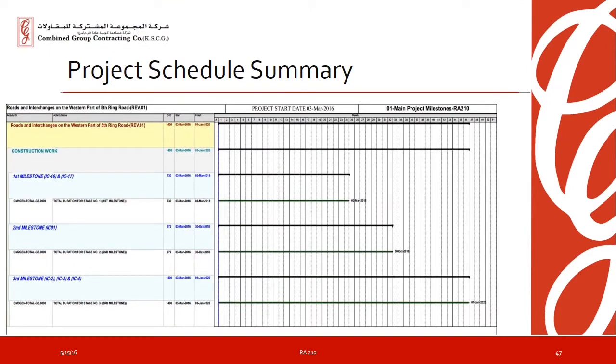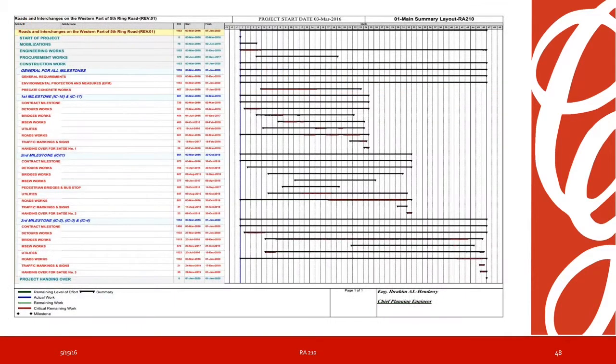The first task normally in a project is developing a schedule or a CPM, and in developing it, the project elements or components have to be broken down into a logical distribution based on a milestone, and then based on an area, and then based on elements, and then their connectivity to the bill of quantity. And it is then broken up into milestones.